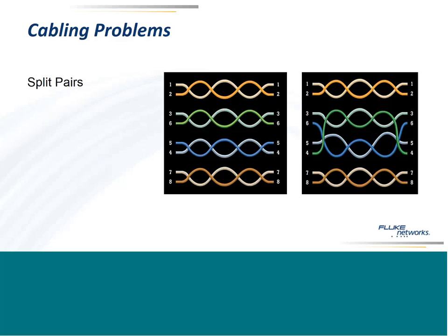And what you get is, especially with Ethernet, which uses 3/6, 4/5 pair in lower speed Ethernet, a transmit and receive pair twisted together and another transmit and receive pair twisted together, and it will not work. Or, as I mentioned, if the cable's short enough, it'll work intermittently. And so this is a very tough problem to deal with.